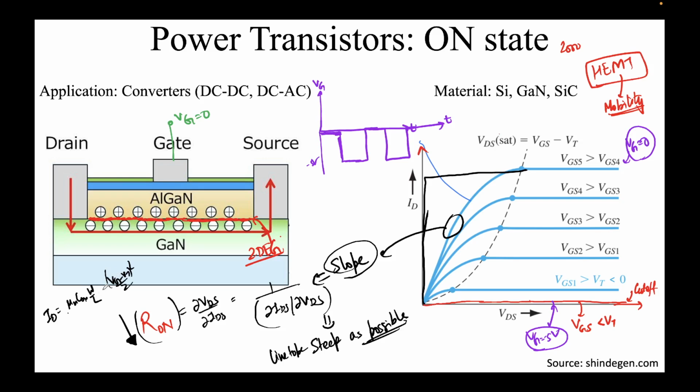And there are various other parameters that are there. It's not like they're not there, but I just want to emphasize this mobility part. So higher the mobility, essentially, higher should be your drain current, and Cox also, but mobility at least you can clearly see over there. W by L is just the geometrical dimension. So we normalize with respect to them, so they do not play as big a role.